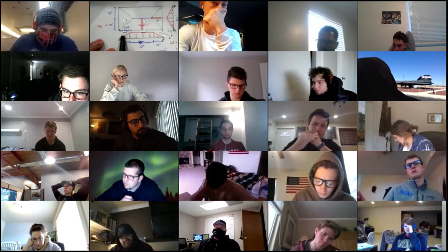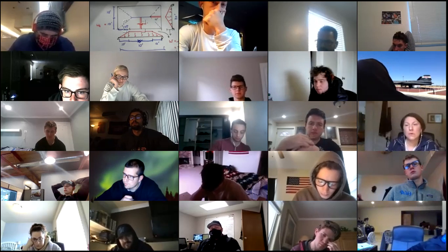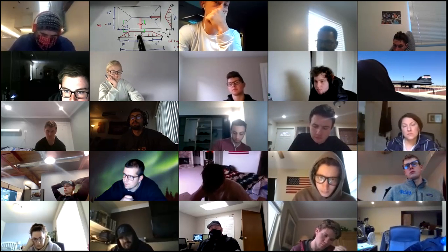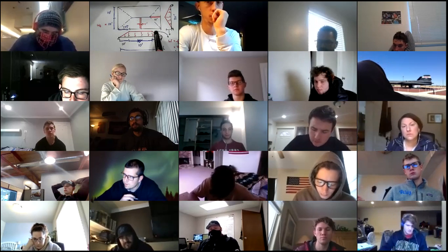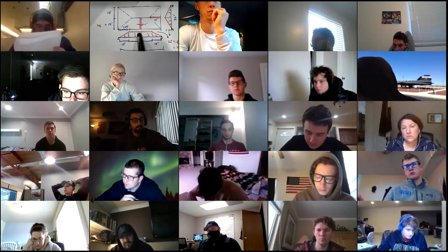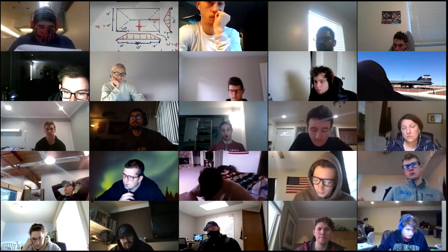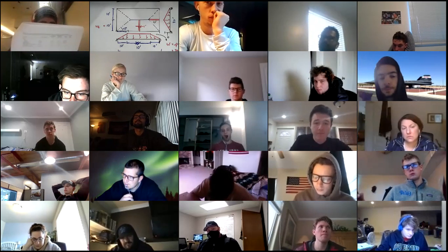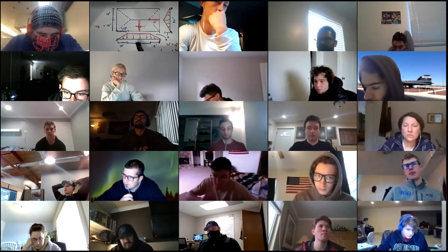But getting rid of that little triangle on this edge, what a gigantic pain. I'm going to estimate the actual maximum moment as though I have the load all the way across, because this little load here doesn't really do a lot to increase the maximum moment. And I know the moment for the straight uniform load is WL squared over 8. And bam, boom, simple, easy. I know immediately what I'm going to design.